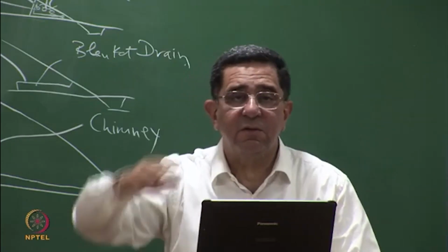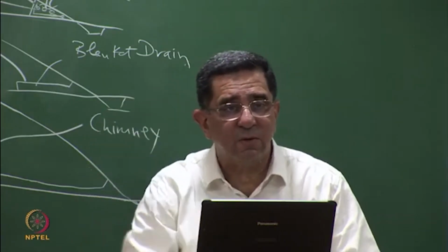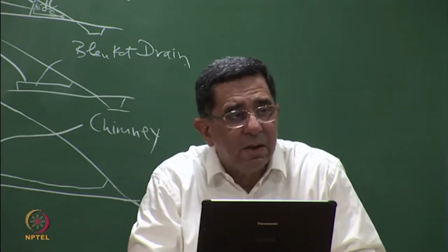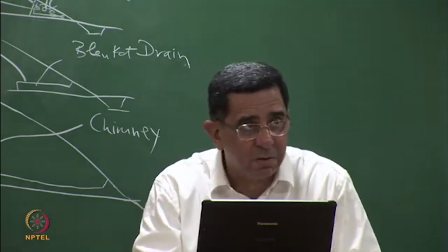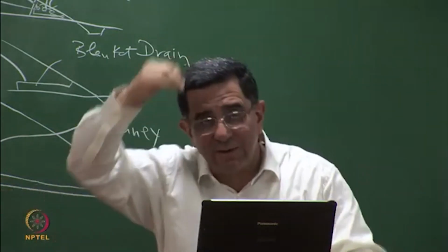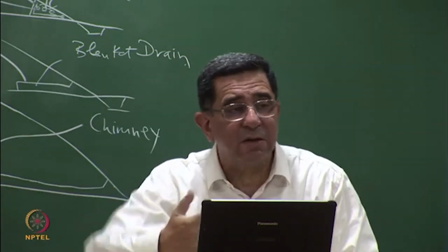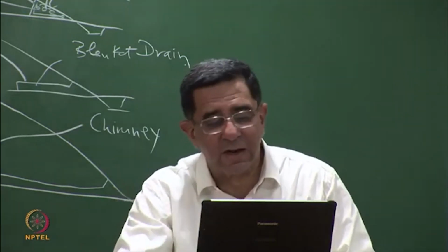If a material is deposited in layers, that means it gets fine, coarse, fine, coarse, fine, coarse. The horizontal permeability is governed by the coarse material, so the horizontal permeability is more than the vertical permeability. That means the water has a tendency to flow laterally rather than to flow downwards in comparison to a homogeneous material. That also has an implication on the phreatic line.